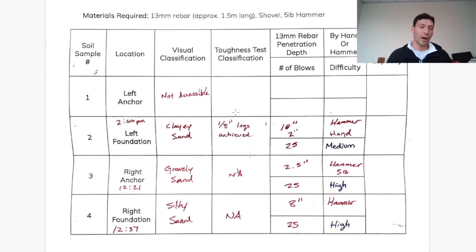And the difference between fine and coarse grained, or fine and granular, is the amount of material that passes the number 200 size sieve. And so you can look up more about that, but the terms that we use in our visual classification are loosely based off of that. Again, we don't have a full laboratory sieve set to do a thorough test and classify it based on grain size, but we look at the soil with our eyes and we pick up the soil and we interact with it in a limited capacity just to get a feel for what the grain sizes are in this soil.